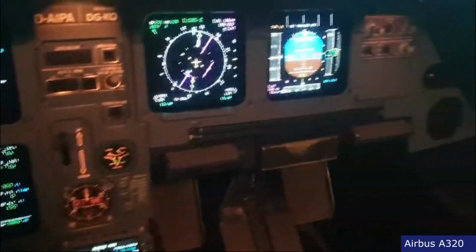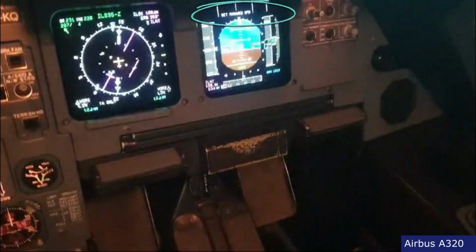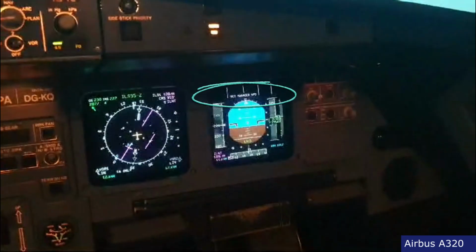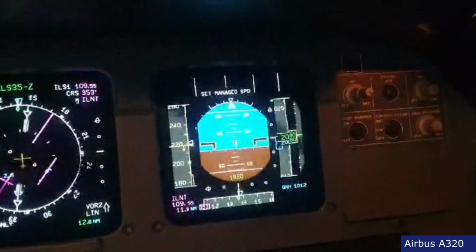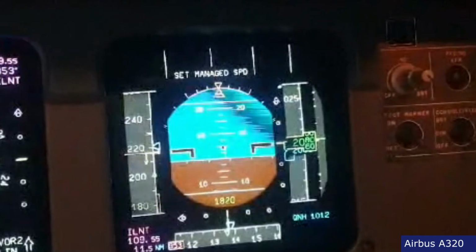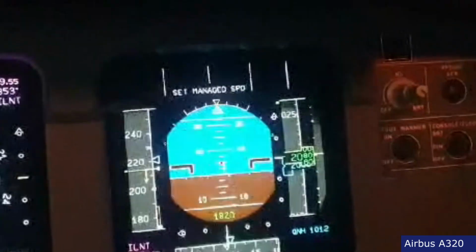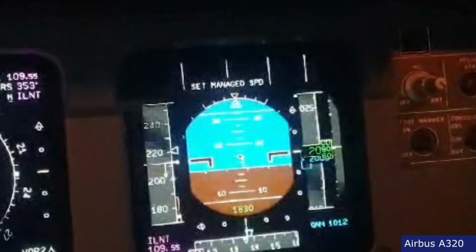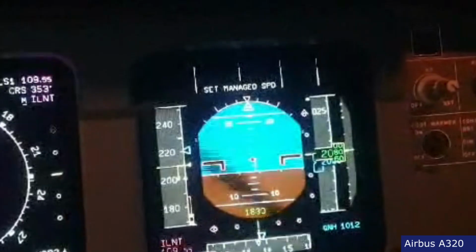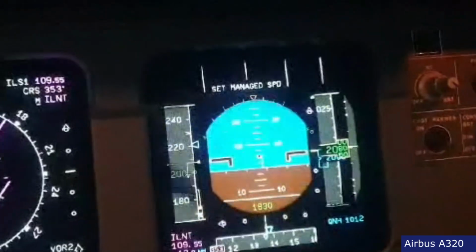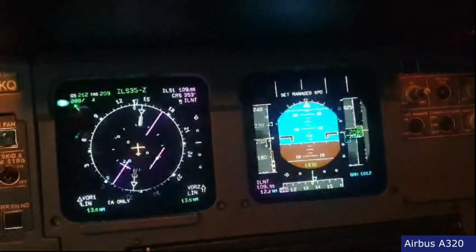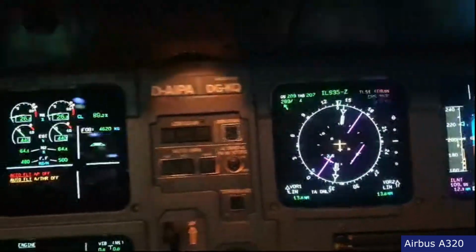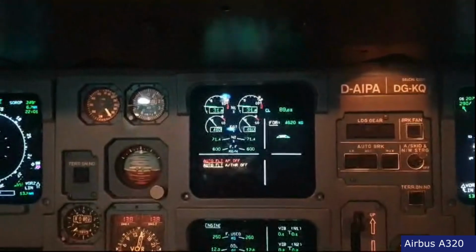Okay, I also disconnected now the autothrust. What I'm going to do is bring the throttle to idle. There we go, manual flight. You see that we are at 5 degrees, which goes to 220 knots, same as in the flight simulator I have at home, in straight level flight. The speed is decreasing. Look at what happened actually. The pitch is slightly increasing. You see, we're nearly reaching 6 degrees in pitch with thrust idle. Now I'm going to add the thrust.